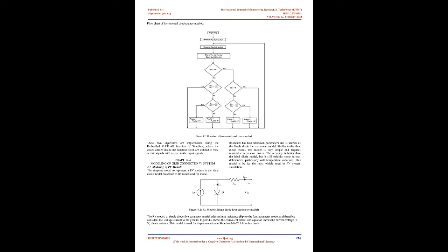The power available from a photovoltaic module at any point along the curve is expressed in watts. Watts are calculated by multiplying the voltage times the current: watts equals volts times amps, or W equals V times A. At the short circuit current point, the power output is zero, since the voltage is zero. At the open circuit voltage point, the power output is also zero, but this time it is because the current is zero. There is a point on the knee of the curve where the maximum power output is located.